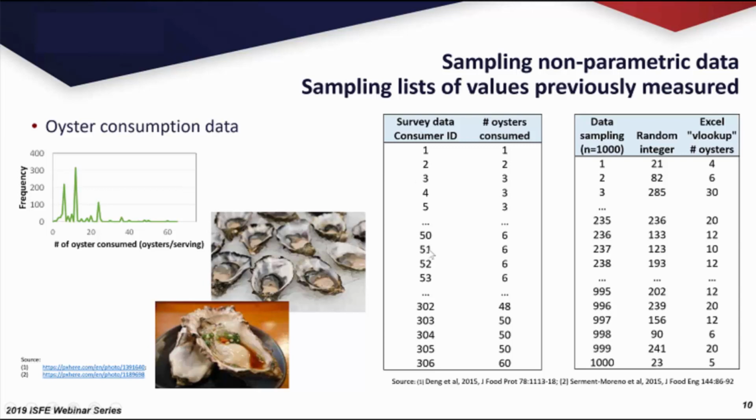So now you can see by changing the package content from 100 grams to 80 grams, my shelf life is 144. And obviously they should have predicted this to happen because if you have less product in the package of the same size with the same packaging film, the amount of water that's entering the product has less product inside, and therefore the impact on the moisture content of the product is higher because there is a small amount of product in the package.